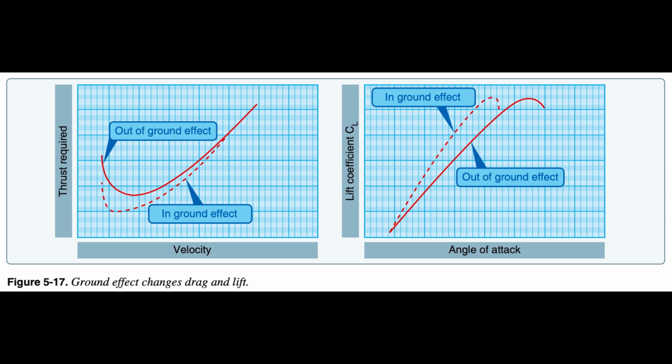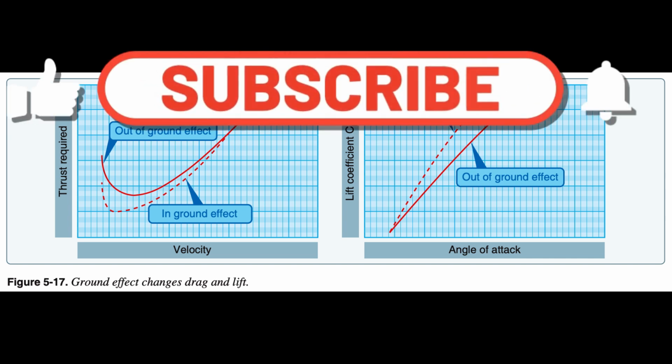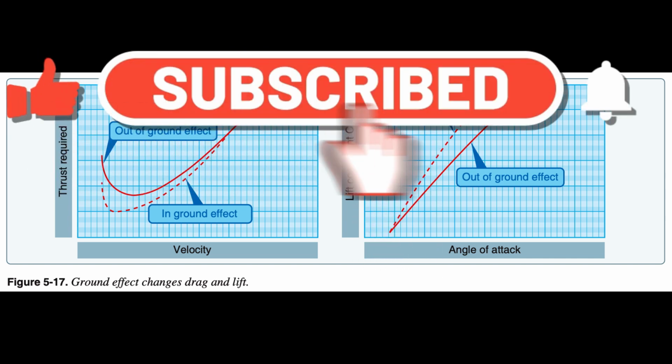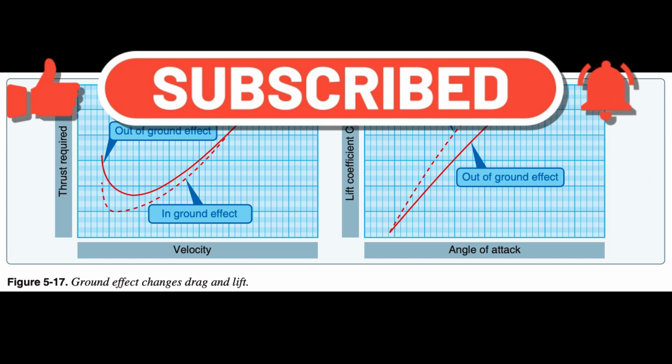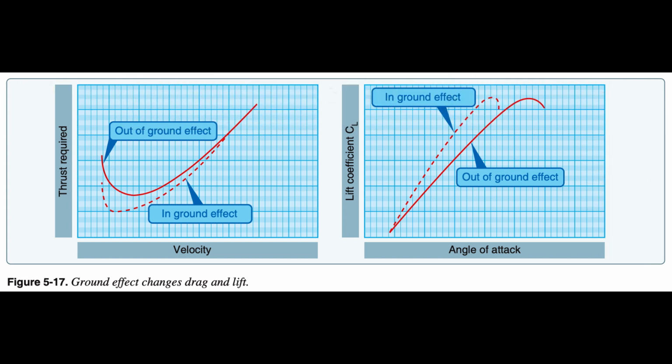Because of the reduced drag and lack of power-off deceleration in ground effect, any excess speed at the point of flare may incur a considerable float distance. As the aircraft nears the point of touchdown, ground effect is most realized at altitudes less than the wingspan. During the final phases of the approach as the aircraft nears the ground, a reduction of power is necessary to offset the increase in lift caused from ground effect, otherwise the aircraft will have a tendency to climb above the desired glide path, GP.